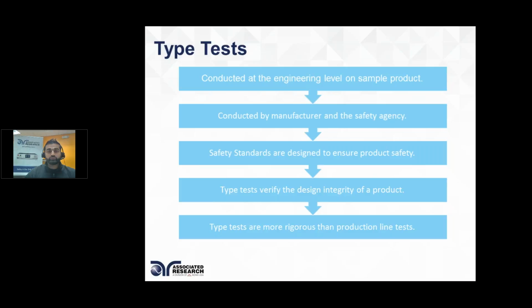Now, these are designed to ensure product safety. This safety is also about end user safety and not being able to cause any shock hazard when the products are out in the field. These types of tests are checking for integrity of the insulation. So you have a product that's going to use line voltage.